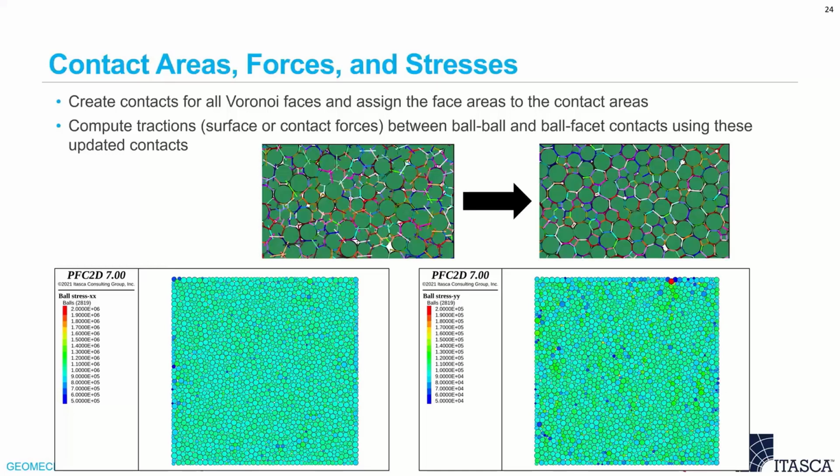So oftentimes the best practice is to actually create a specimen, install the stress, and then trim it to a smaller container size. Because also, as you might see in this plot, the balls actually end up being aligned with the boundary, which happens. This assembly was just generated first by generating a bunch of balls, blowing up their radii, allowing them to equilibrate, and then calling the ball tractions command.